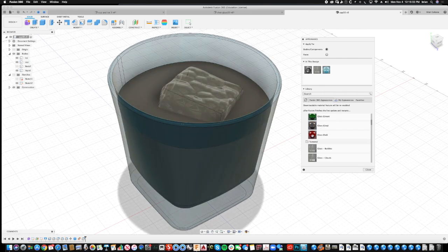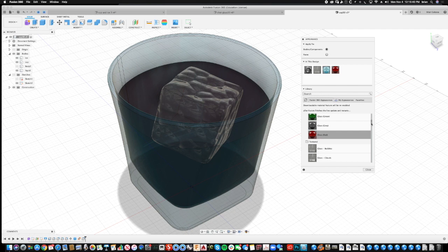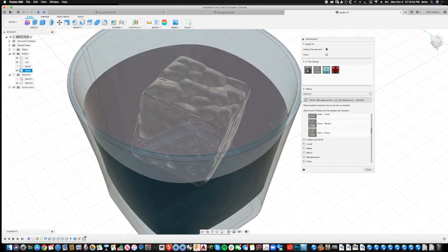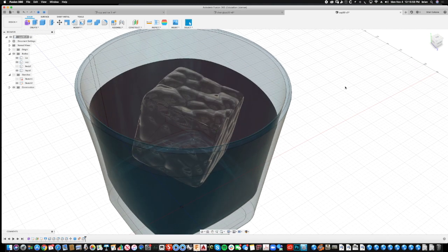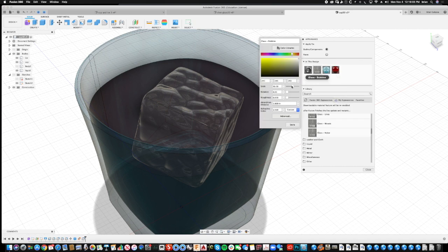So last time we used this transparent plastic red. Oops, that says glass. Let's go down. Kind of curious. Actually, I'm going to leave that, just see what it looks like. And the glass kind of looks a little bubbly. You see that? Because of that material we chose. So let's go back to repeat appearance and double click on the glass bubbles, and we'll just change the scale.